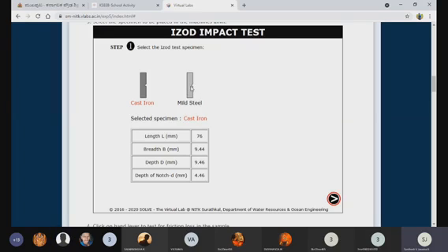Note where exactly 25 mm is and indicate it with chalk or anything else to make the indication exact. Once measured, at that point we groove it. That groove will be 2 mm. Don't exceed more than 2 mm; if you exceed it, the procedure will be wrong. According to the ASTM standards, the groove depth must be exactly 2 mm.